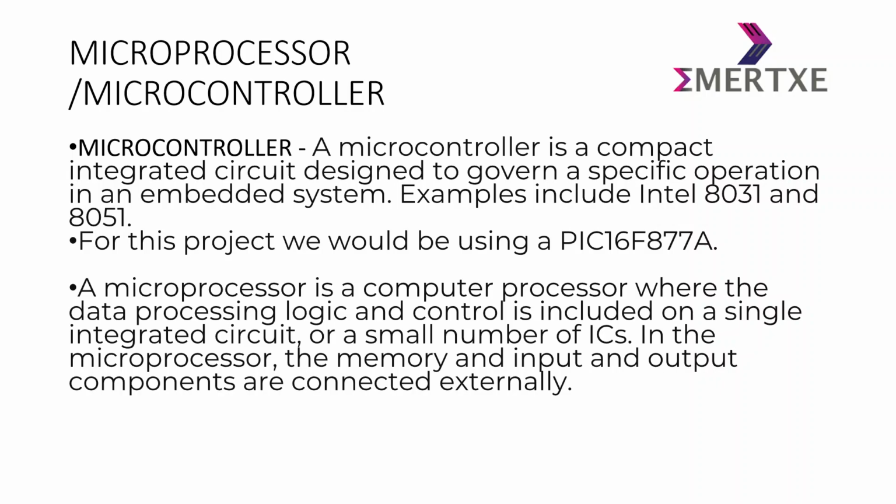A microprocessor is a computer processor where the data processing logic and control is included in a single integrated circuit, or a small number of ICs. In a microprocessor, the memory and input and output components are connected externally.